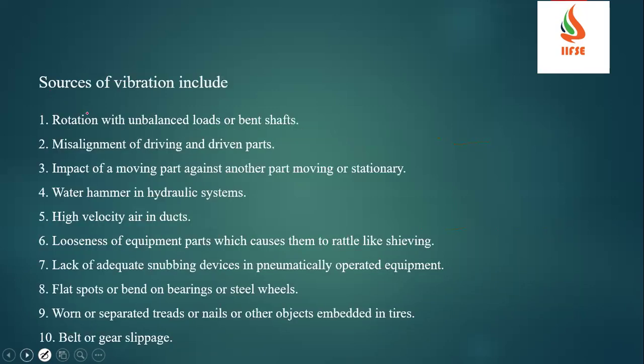If you see, the sources include rotation with unbalanced loads, which will give a vibration. Misalignment of driving and also driven parts, impact of moving parts against another moving part. For example, in a gearbox which is moving this way, that also gets interacted. Water hammer in hydraulic systems, high velocity air in ducts. High velocity air in a duct will also give vibration in the ducts.